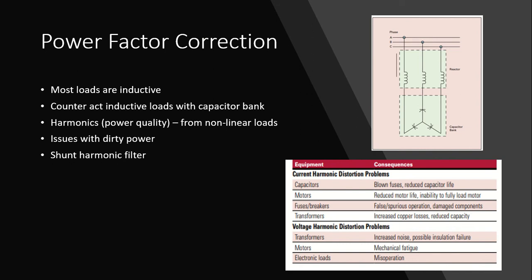Voltage harmonic distortion problems can lead to mechanical fatigue and eventually failure in motors, and then in transformers, increased noise and possible insulation failure, as we see there.